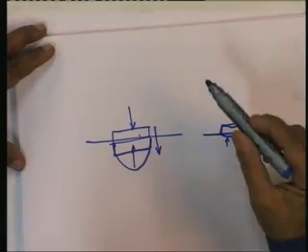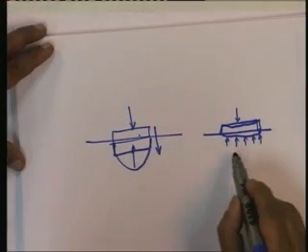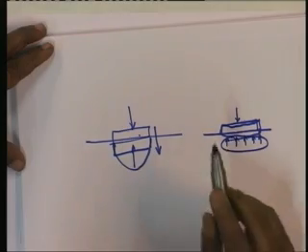So, it is the relative rigidity or flexibility of the foundation with respect to the soil which controls this pressure distribution, and in general this pressure distribution could be non-uniform. It need not necessarily be uniform. However, we shall be making a simplistic assumption, an idealization, that this foundation contact pressure is actually uniform. This considerably simplifies the computation of stresses inside the soil without incurring huge loss of accuracy or large errors. Let us go further.